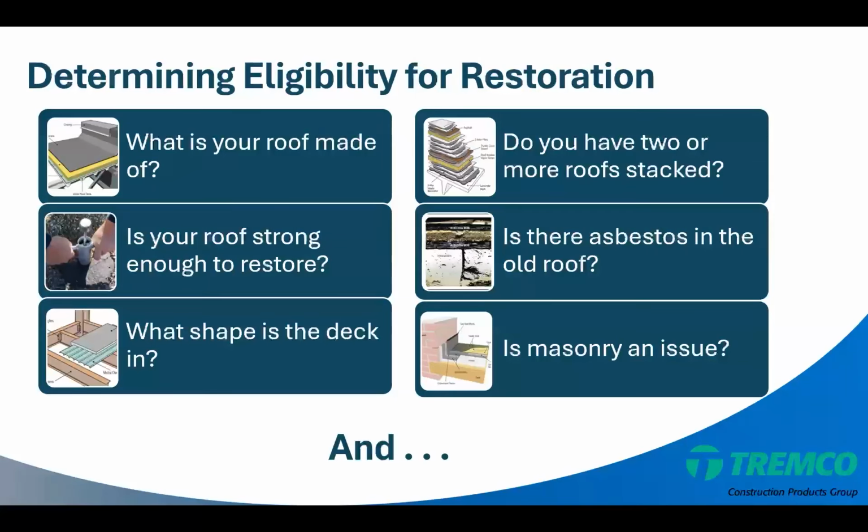In many situations, building code might limit your ability if you've got one roof and then you install another membrane or another roof system over it. But in the case of restoration, because the top layer of the waterproofing is monolithic, this does not mean that there's another roof over a roof. So in many situations where facilities believe that they have to tear off and replace down to the deck, doing a restoration under building code allows us to move forward, where if you were just applying a roof membrane over a roof membrane, you would not be able to do that.